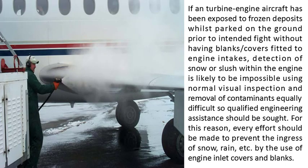If a turbine engine aircraft has been exposed to frozen deposits whilst parked on the ground prior to intended flight without having blanks or covers fitted to engine intakes, detection of snow or slush within the engine is likely to be impossible using normal visual inspection, and removal of contaminants equally difficult, so qualified engineering assistance should be sought. For this reason, every effort should be made to prevent the ingress of snow, rain, etc. by the use of engine inlet covers and blanks.